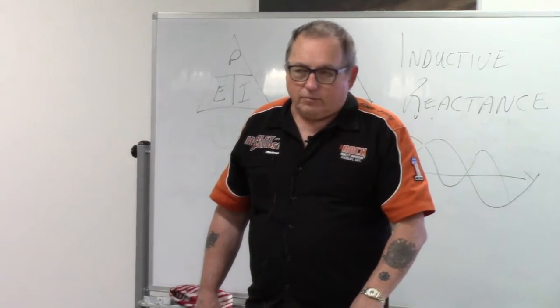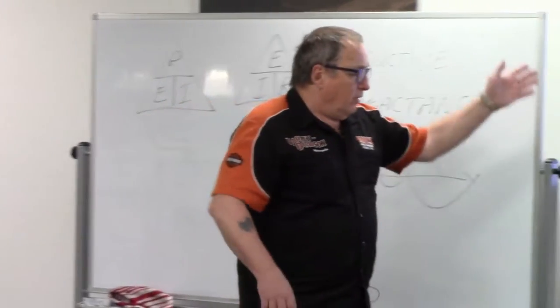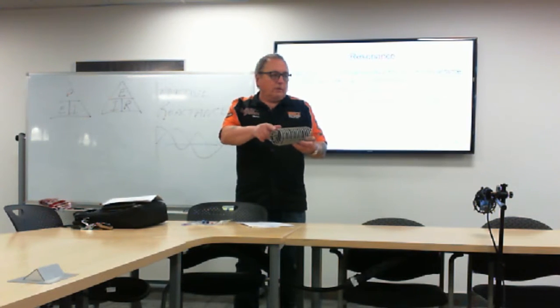We talked about varying inductors, but we didn't talk about varying capacitors, did we? We didn't really talk about capacitors enough, I don't think. And I was following this, and it's not a good way to do it. What they usually do is there's a roller that goes along here for the change, and that roller is your output. This is your input, and this is your output. This is not connected. So that roller will determine your inductance. As it touches each coil, it changes how many turns are in the coil.